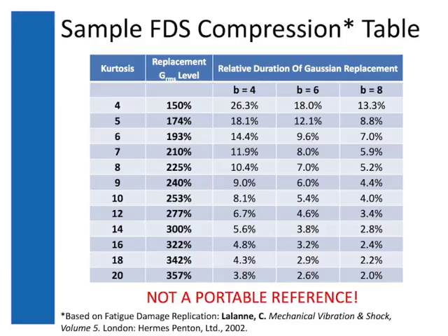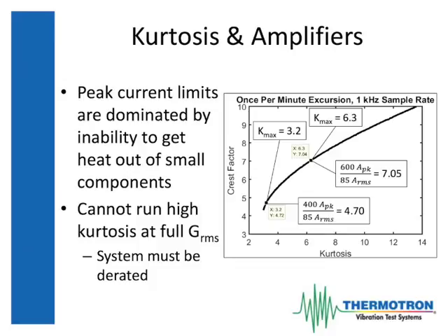Now, you do have to turn up past the 200% level, and someone out there is thinking, okay, but my shaker can't actually do that. So let's talk about that for a minute. Speaking as a representative for a company that makes shakers and, as an aside, makes controllers to control them, I want to talk for a moment about the process of running kurtosis specifically on an electrodynamic shaker powered by amplifiers, which is a stack of inverters.